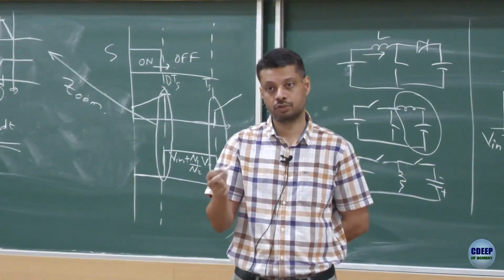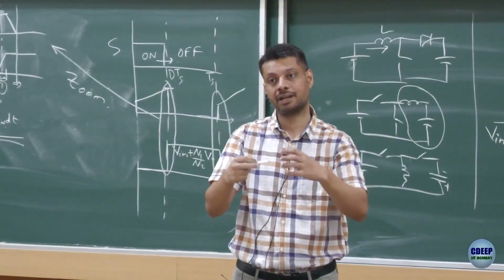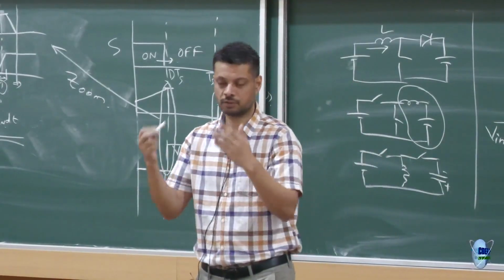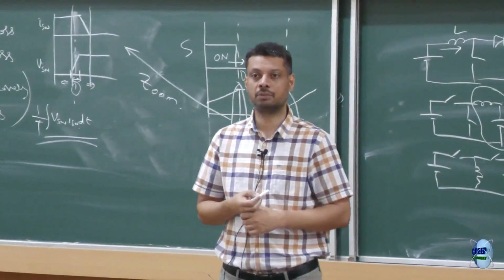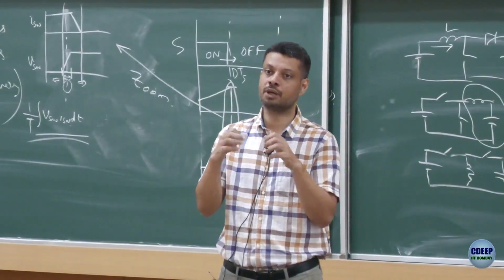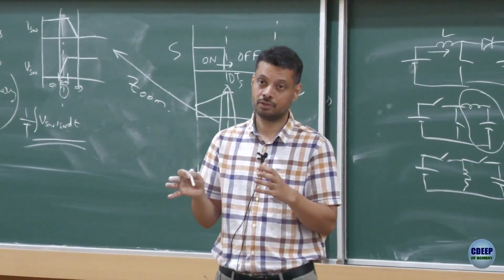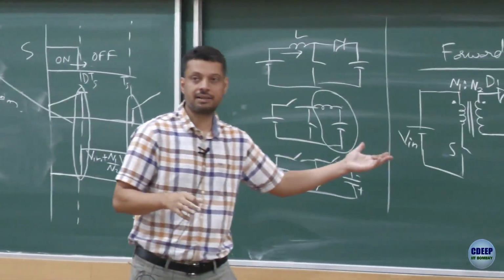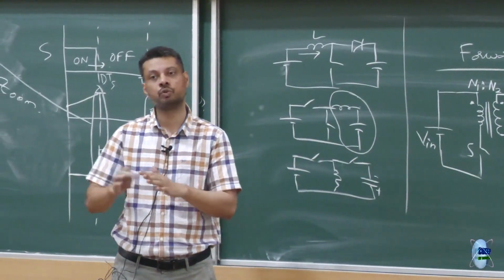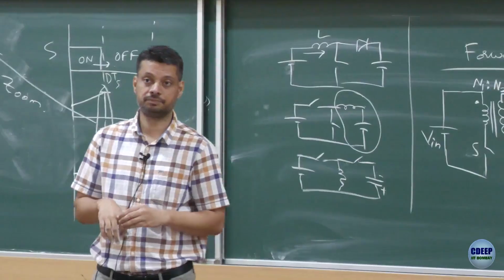If you use a buck boost, practically all the 350 volt energy is dumped into the inductor and then transferred to 400. Of course you need to derive a detailed equation, but broadly speaking, 350 to 400 would come out more efficient using a simple boost than a buck boost. Same thing here: instead of using a buck boost, using a dedicated buck or a dedicated boost has more potential of giving you better efficiency.